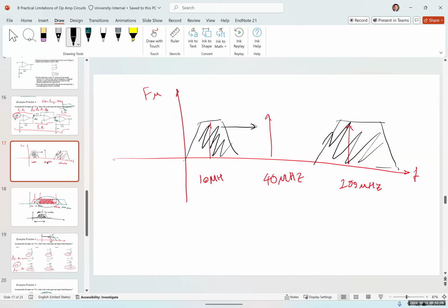Another scenario is that, imagine you want to pick this and this station, but this in the middle is noise. Then we can use something which is called a notch filter or a band stop filter, which is going to stop a certain band and pass other frequencies.